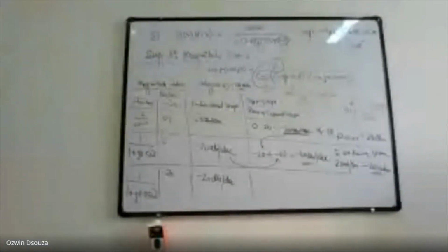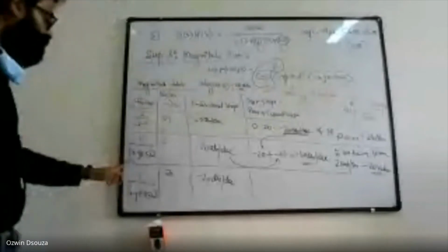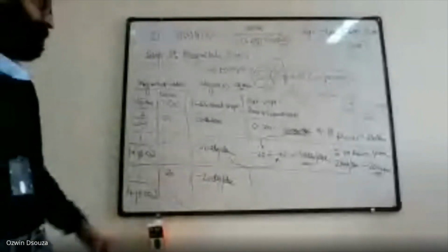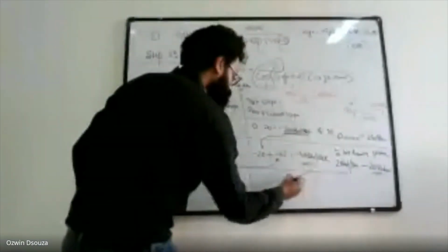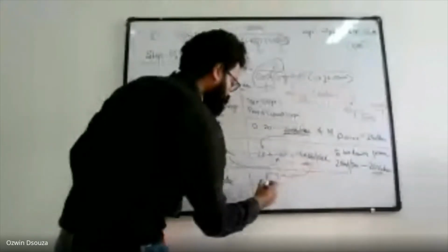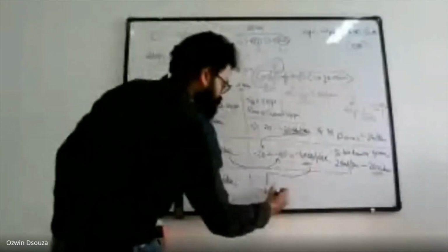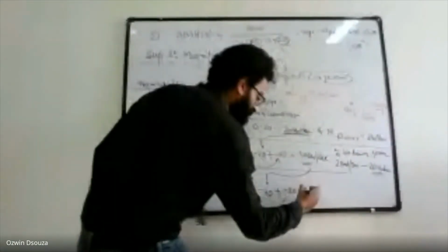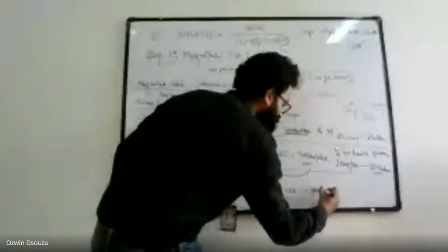At each corner frequency, the poles or zeros start to appear in your system, right? Now let us look at the third factor. So the third factor gives an individual slope of minus 20 decibel per decade, due to which the net slope becomes, okay, what is the previous slope? The previous slope was minus 40, right? And the current slope is minus 20. So the net slope becomes minus 60 decibel per decade.